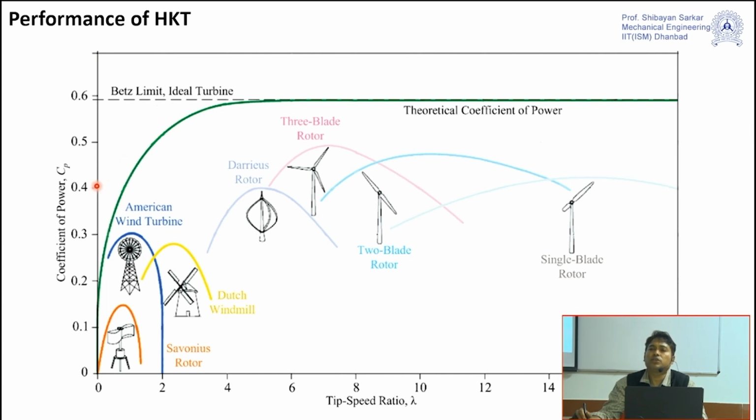So why should we use this type of turbine? Because with a conventional hydro turbine, you can get more than 80%, 90% efficiency. So why do we go for this particular turbine? This type of turbine is called a zero head turbine. That means it works even when the river flow height is very low, even less than 3 meters, 4 meters. We can put this turbine in a normal canal also, where water depth is 2 meters, 3 meters, which is more than enough. The main concern here is how much water speed is available in the canal or channel.